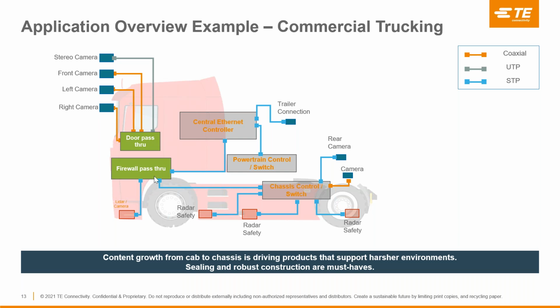those pass-through connections often require then a connector that is designed specifically to mount into a panel and be secured, so that if you think about a pass-through in a door truck, you don't want, over the course of multiple months and years of driving, to have connections that are now vibrating loosely inside of the door panel as you're driving down the highway. There's specific needs in industrial and commercial transportation to be able to securely attach those connector systems in a panel, in a door, for example, or through a firewall. And those types of products today in the automotive environment are really not even addressed. And that's what we'll be addressing here as we talk further.